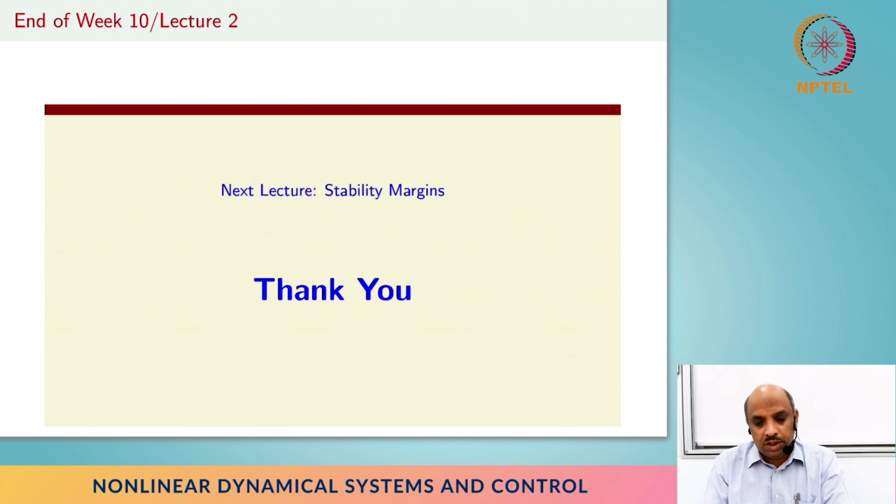What does this mean? Suppose we cannot solve this particular problem through all these very difficult equations, can we actually do something else? Can we get inverse optimality? If we have a stabilizing controller, can I know that there is some cost that is going to be minimized for that particular controller? At least that will shed some insight into what we are minimizing. And moreover, can we get some stability margins for that kind of approach, so that within feasibility we can pick a controller that gives margins also, right?